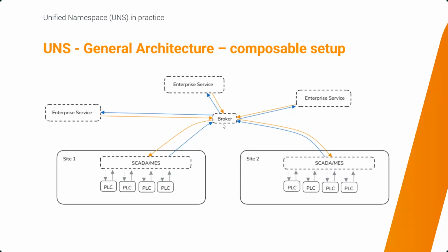If I take a look at the broker itself, I would propose here to have an MQTT broker that uses flat MQTT, since in general, enterprise services generally do not support SparkplugB yet. So this is actually an IT layer and the IT field. So we use more flat MQTT than the SparkplugB protocol.